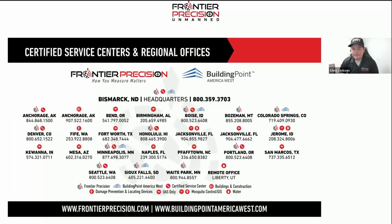The next question that we have asks, does the use of LiDAR require a restricted flight envelope? For example, maximum airspeed, maximum or minimum flight altitude, ideal flight endurance time, that type of thing. So it's going to be highly dependent on the sensor that you're using. The sensor that I talked about, the Voyager, is kind of the top of the line. It's using a more powerful scanner where it gives you more range. So with that sensor and the higher quality IMU, we're able to fly higher and fly faster.